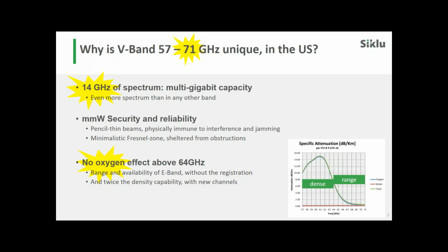Again, our link budget calculator has been up to speed on rain fade calculation for a good amount of time because we were doing E-band calculations as well. So we utilize the same database, same algorithms. We've just plugged into our link budget calculator the additional channels and the data of the radio for the 614TX. So if you want to compare the behavior of the 600 versus 614TX in any city in the US, go to the link budget calculator, use the lower channel, put a higher channel, so that you can go further out. But as soon as you put rain and availability matters to you, you will see that